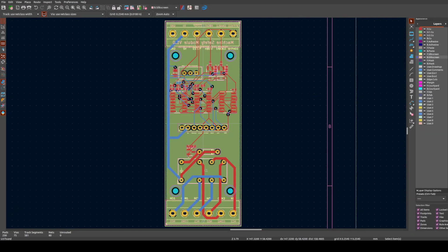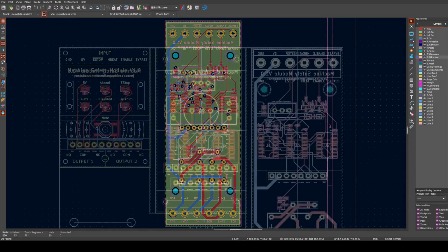I have 2 internal ground planes and signal and power routing on the top and bottom layers. Because I have multiple PCB positions in my enclosure, and because I'm already paying pick and place fees for inverters and NAND gate ICs, I added a couple of additional boards.